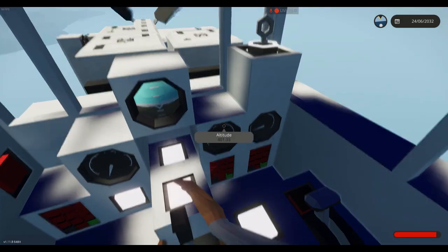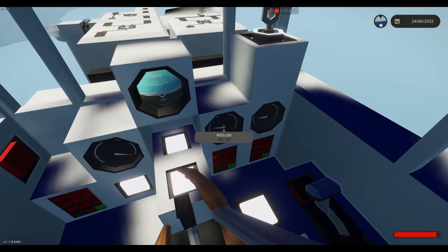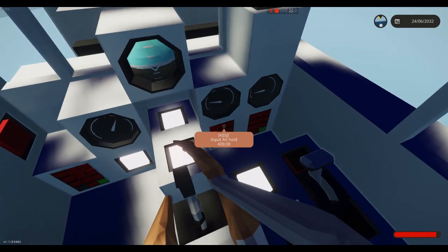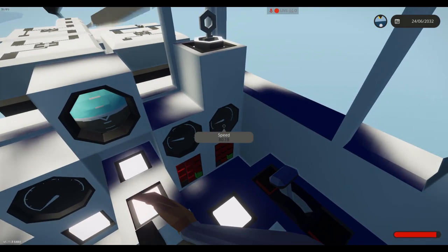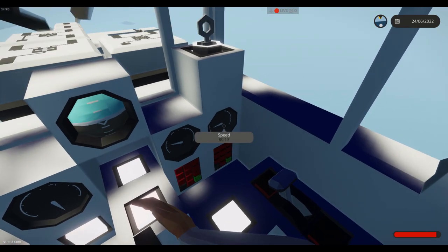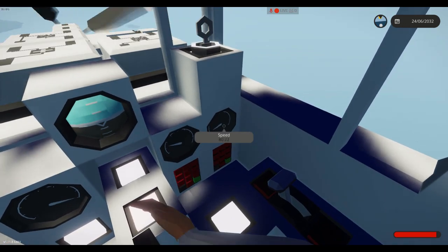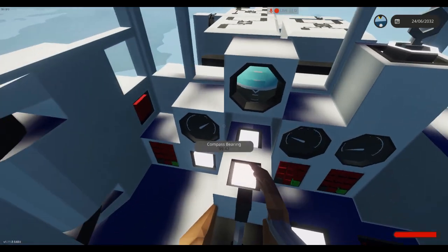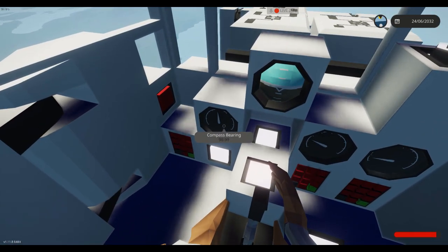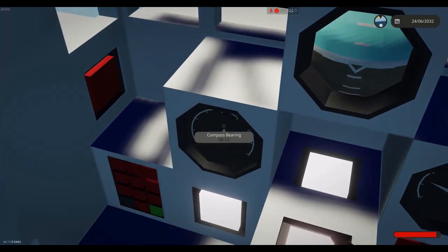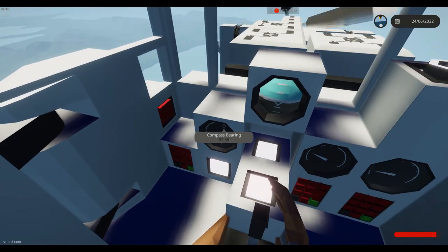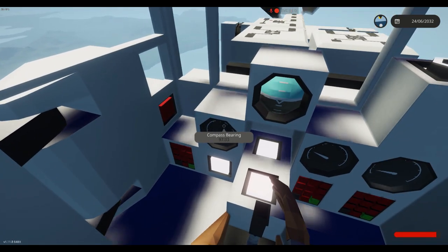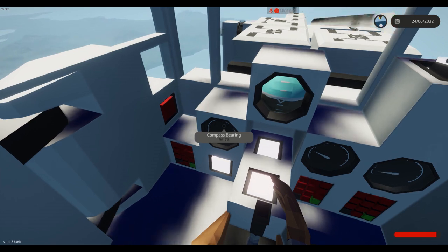You can see our altitude hold system from earlier is working just fine. We put in 400 and it's holding at a value of 401. Our speed hold works almost perfectly. We have put 80 and it's holding at pretty much right there at 80. Let's take a look at our compass. Still just very slowly trickling. So the positive to this, that it's taking this long, is it means it is most likely not going to overshoot at all. Or if it does, it'll only overshoot, it won't overshoot by a full value.